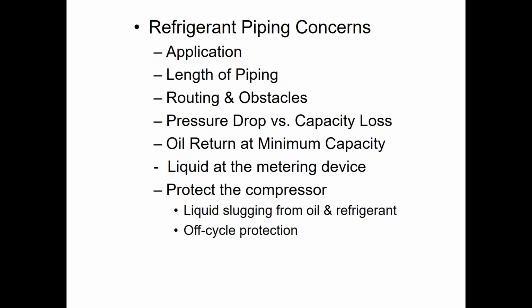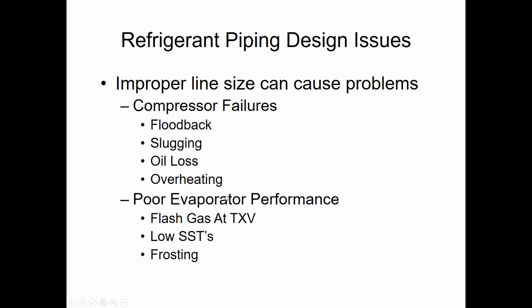So all of our vapor pipes, our discharge lines, our hot gas bypass lines, suction lines, all the vapor lines, that's where we have problems returning oil if our pipe sizing is incorrect or if there are unnecessary traps. We're going to cover all that little by little, starting with the suction.